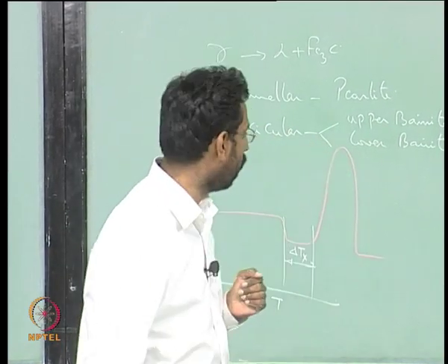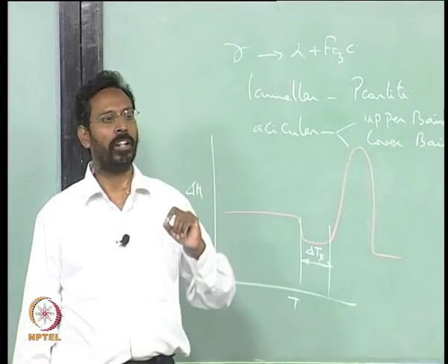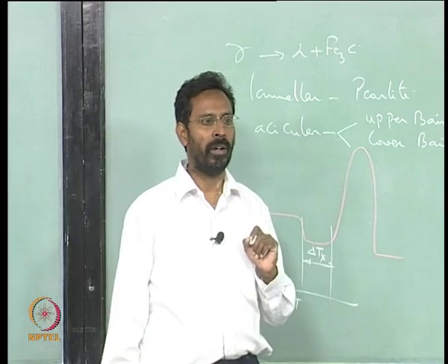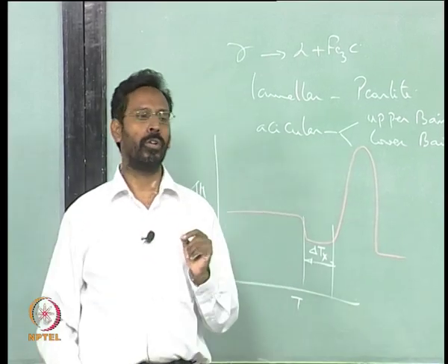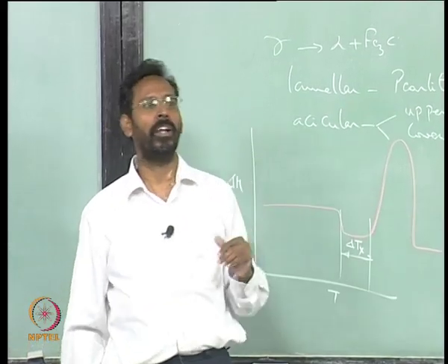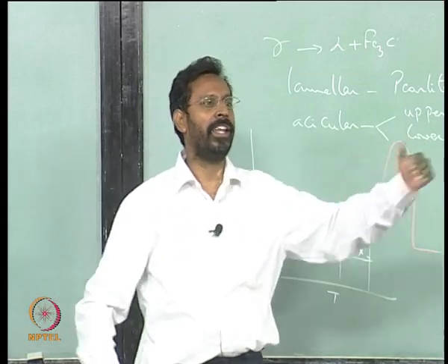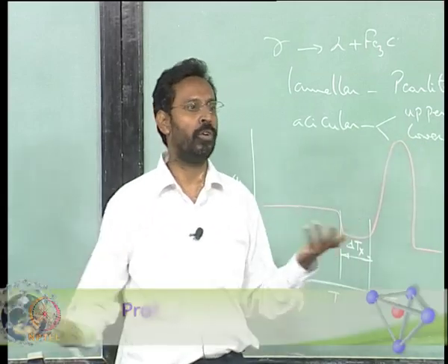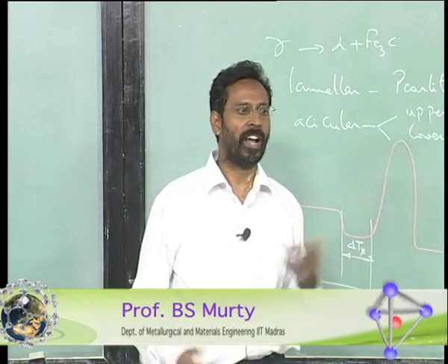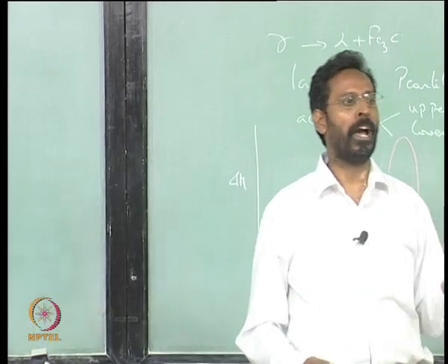There are examples like that, where basically you induce small nanocrystals, so that small shear bands form, and then there is no growth of that. Because each particle will act as an obstacle for the shear band to grow. So, as a result you have some kind of obstacles for any crack propagation, and that gives you higher fracture toughness. Fracture toughness is always related to either crack initiation or crack propagation.